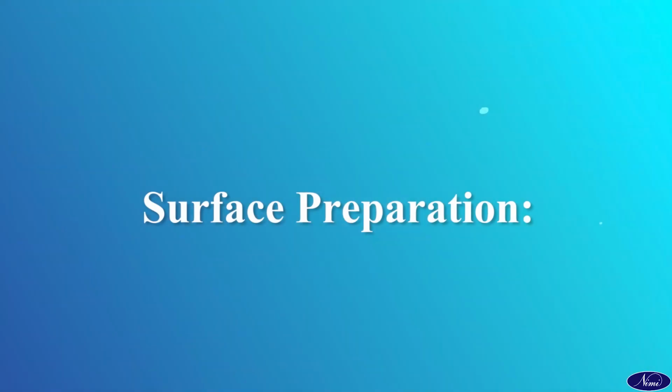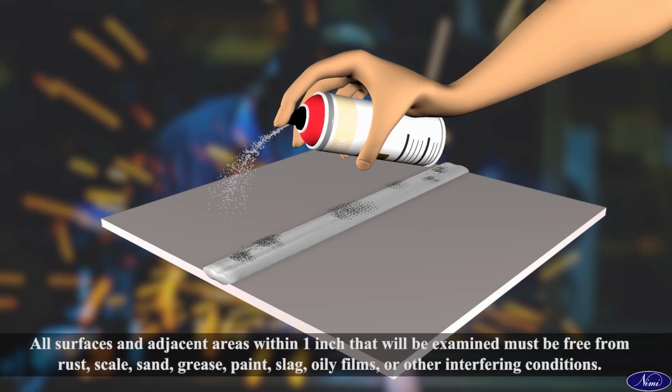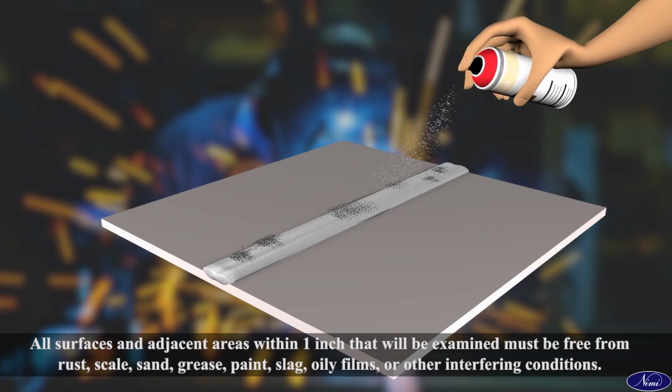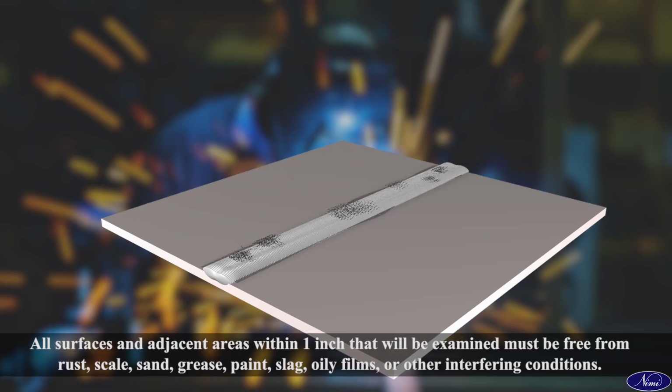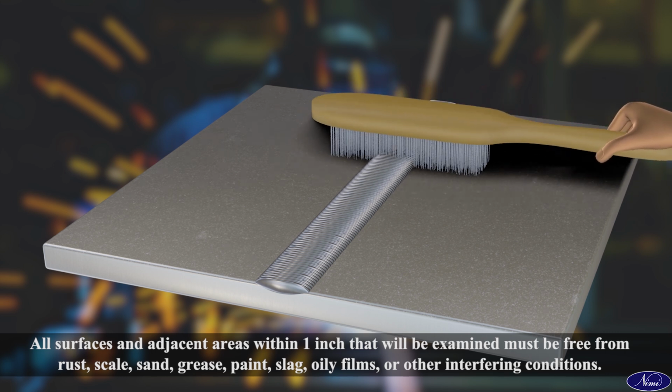Surface preparations. All surfaces and adjacent areas within 1 inch that will be examined must be free from rust, scale, sand, grease, paint, slag, oily films, or other interfering conditions.